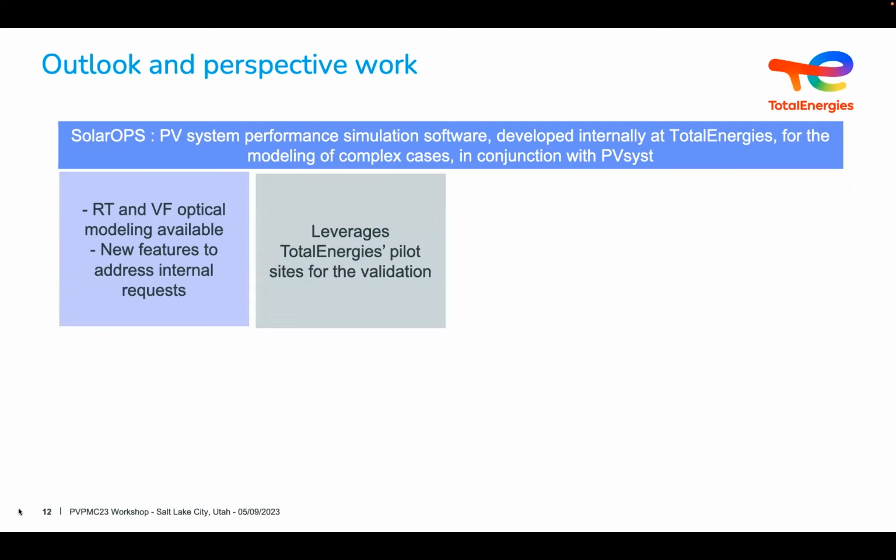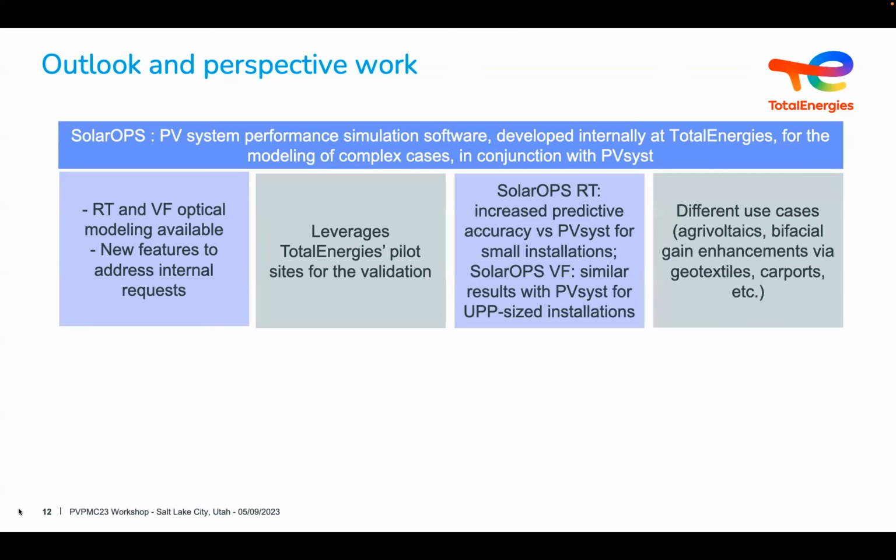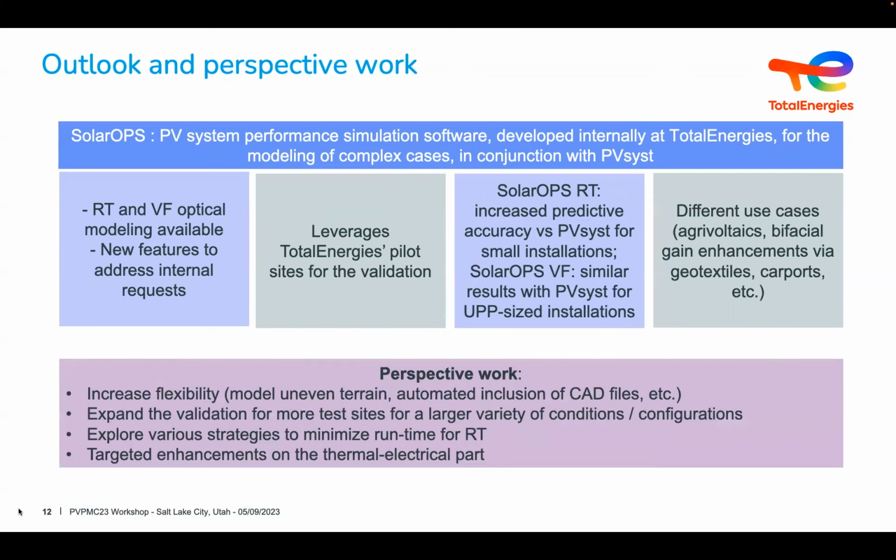We are leveraging our own pilot site for the validation, and as discussed, the ray tracing has increased predictive accuracy versus PVsyst for small installations, while for large utility-scale PV plant installations, the SolarOPS view factor and PVsyst yield almost identical results. And I showcased some different use cases.